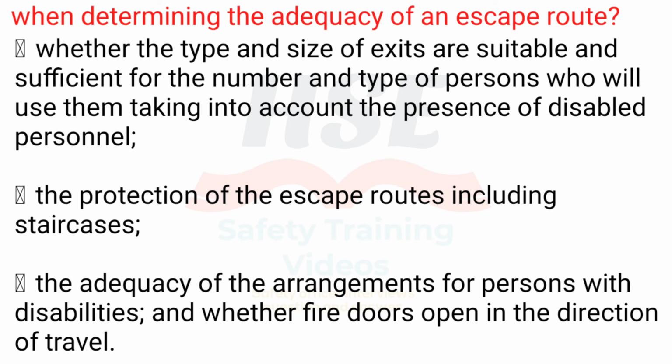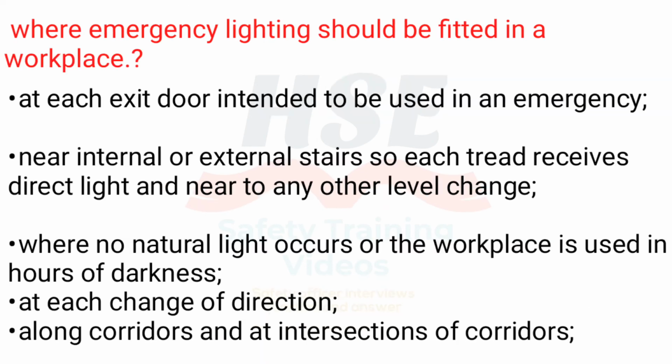Whether the type and size of exits are suitable and sufficient for the number and type of persons who will use them, taking into account the presence of disabled personnel. The protection of the escape routes including staircases. The adequacy of the arrangements for persons with disabilities, and whether fire doors open in the direction of travel.